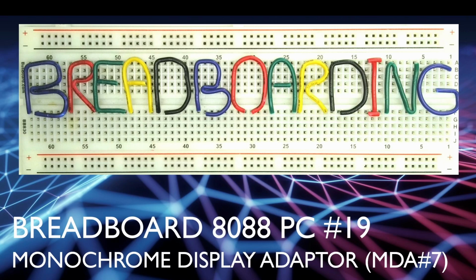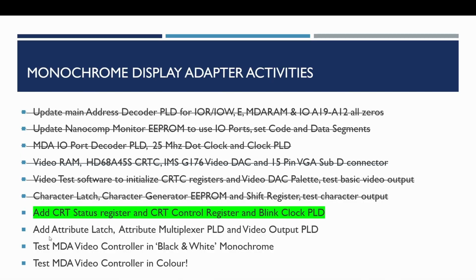Welcome to Breadboarding. This is video 19 in the Breadboard 8088 PC series, and it's the 7th video looking at developing the Monochrome Display Adaptor video controller. In this video we're going to be doing just some preparations for the last push on getting the video controller fully working. We're going to be adding the CRT status register, control register, and also the Blink Clock PLD, which is necessary for doing the timing for the cursor and the character blink.